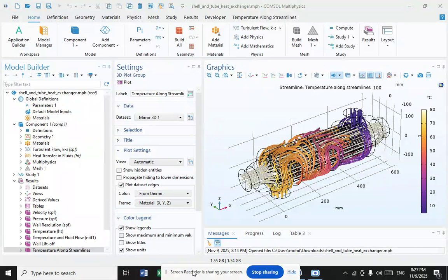A gasket plate heat exchanger has a heat region from corrugated plates. The gaskets function as a seal between plates, and they are located between the frame and pressure plates. Fluid flows in a countercurrent direction throughout the heat exchanger, and efficient thermal performance is produced. Plates are produced in different depths, sizes, and corrugated shapes.